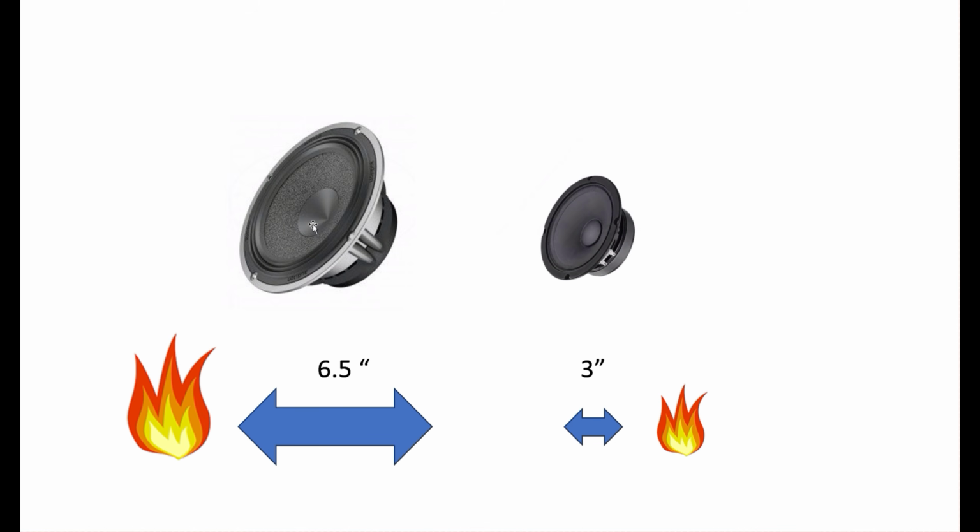So, the same way as we have a high frequency limit, we have a speaker with a low frequency limit, and in the case of low notes, when you're looking at 100 hertz, then the 6.5 is going to win because it's got bigger cone area, bigger X max, and a bigger, stronger motor that can push more air and deal with more heat, right? So between the two, this is going to be the winner to play lower notes.